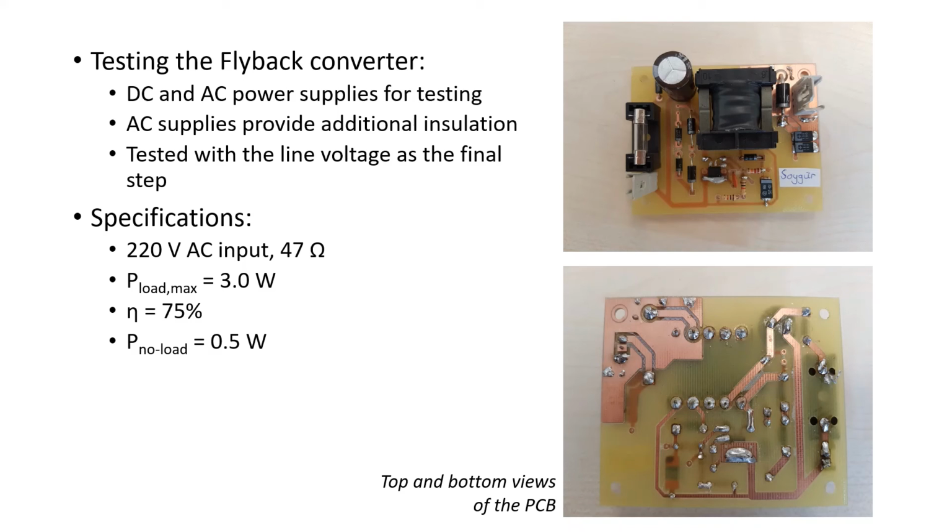I ran my final test using the actual line voltage, and I measured a maximum load power of 3 watts that provided 75% of efficiency. And the no-load power consumption was 0.5 watts.